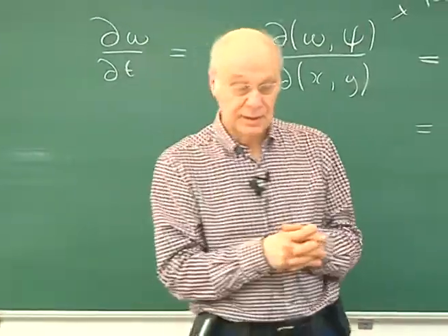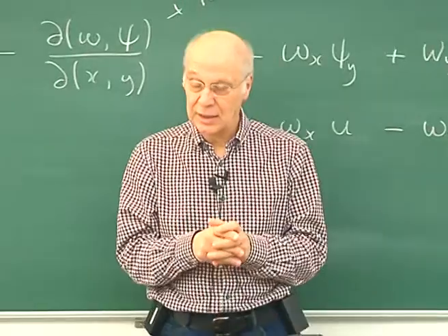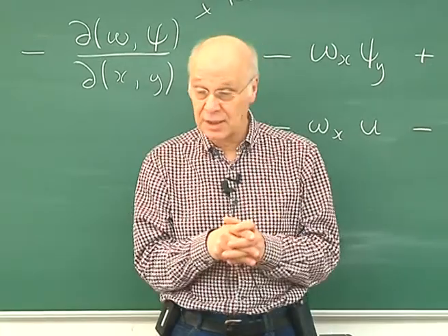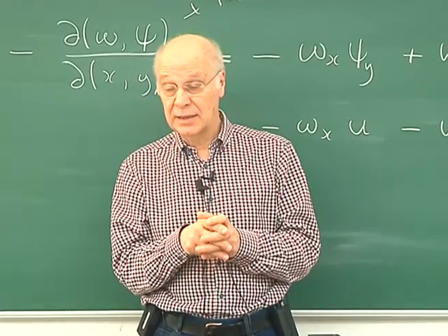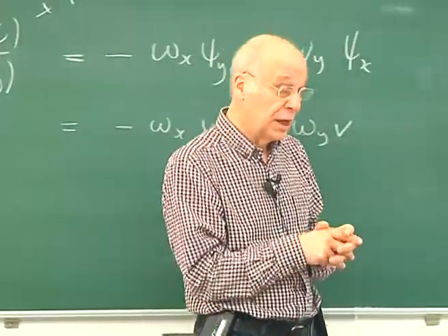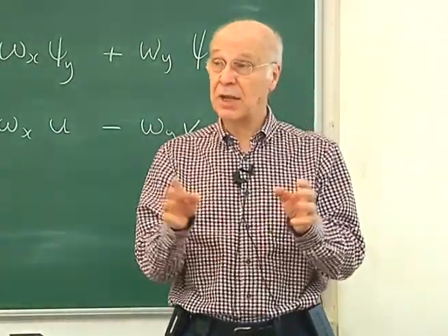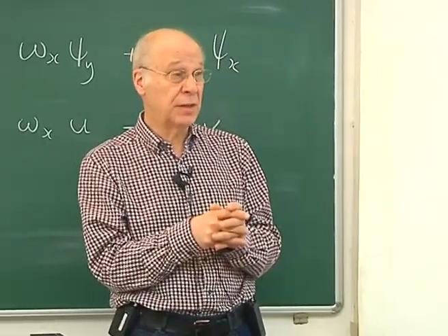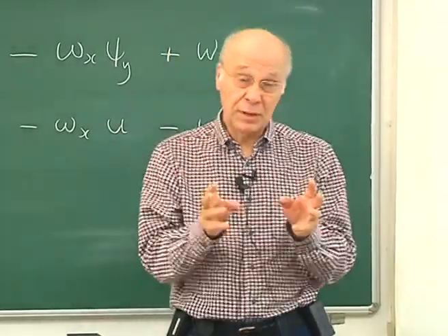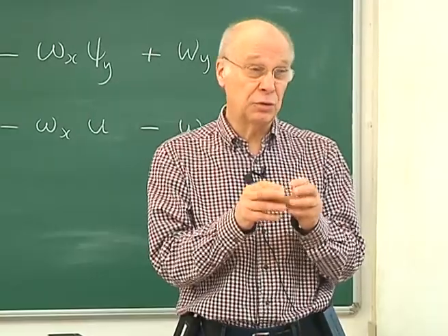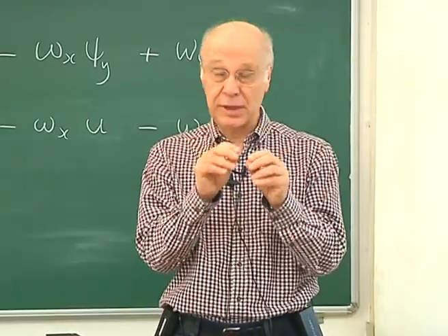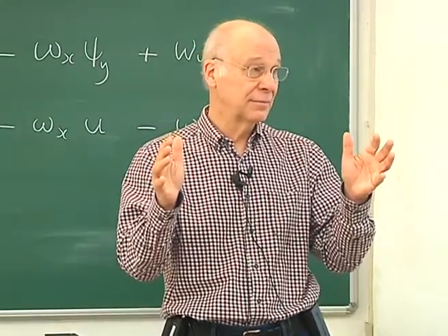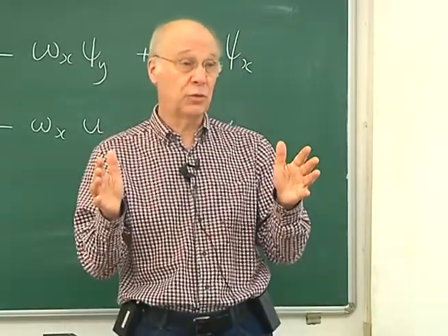Okay. There was a little quick discussion about non-Cartesian grids, because we do use polar coordinates and other things, and the staggered grids, and also an issue of, are you going to have a conservative system? So I wrote out what was needed for a global conservation of momentum. So numerically, in solving the momentum equation, you're not doing a perfect job at each point, but you can make sure you do an exact job on the whole domain. And that's so that I get the total force is 0.